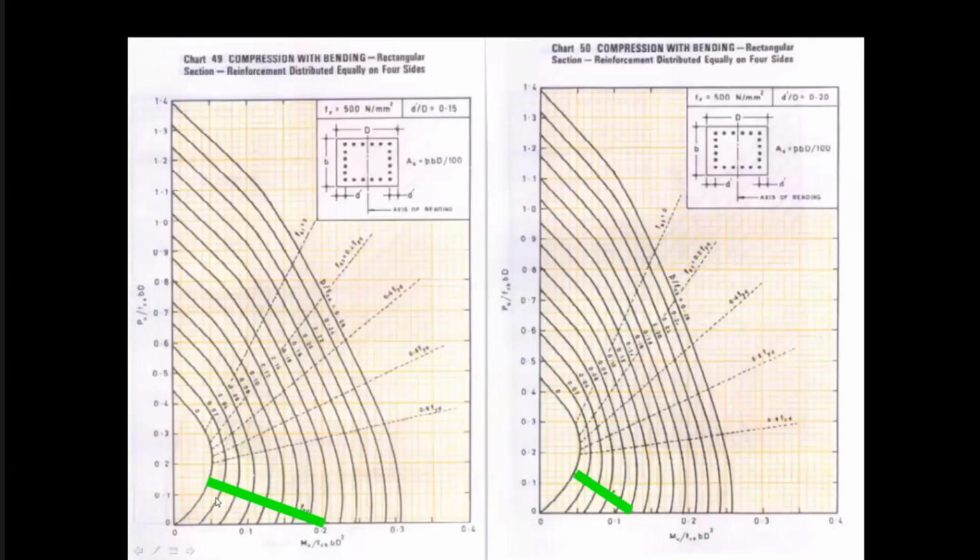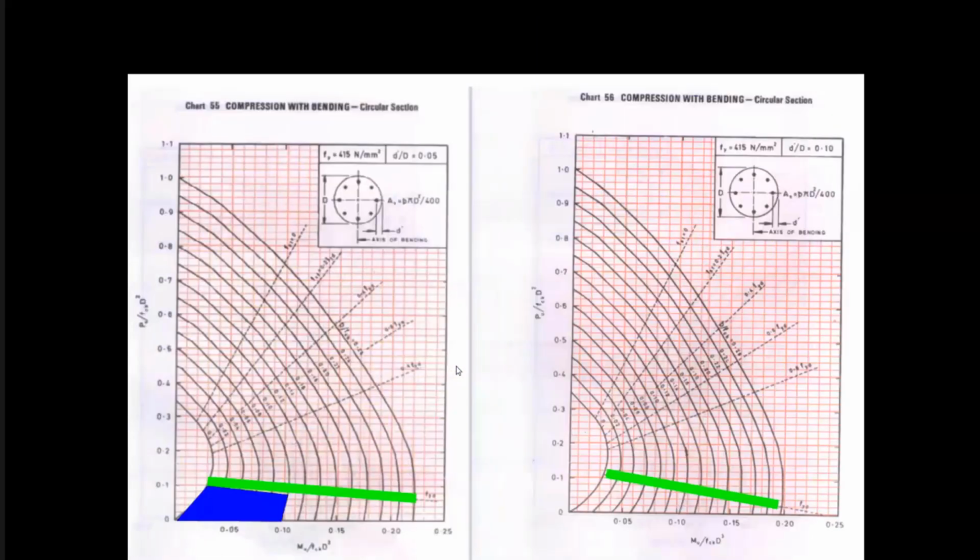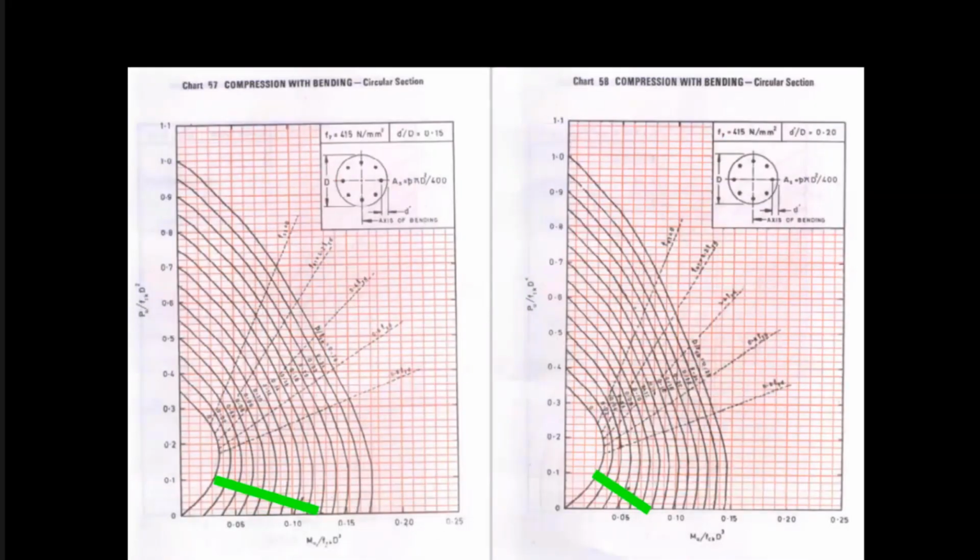Let's look at this a little more on the circular column. Circular column is very popular in the country. In fact, circle is the worst cross section that should be used in structural engineering. Why? Because much of its mass moment of inertia is sitting at the axis. And so for bending, it's the most inefficient section. The topmost fiber reaches the extreme stress. The section has reached the extreme stress. This is the most inefficient section.